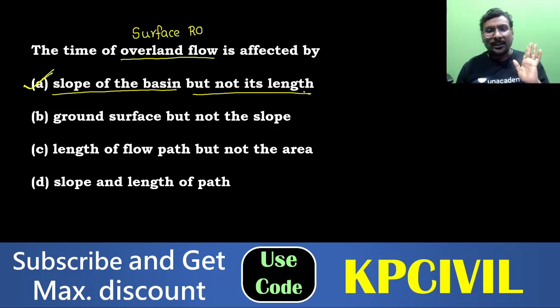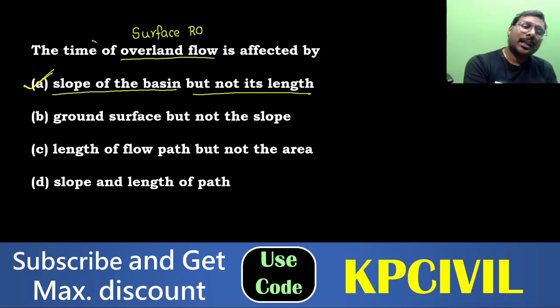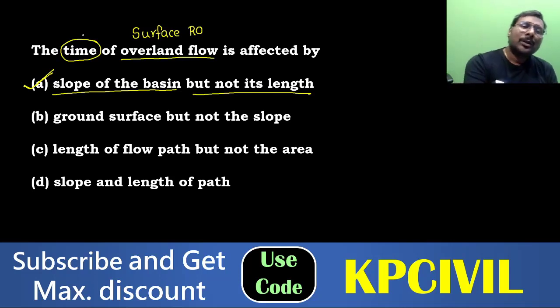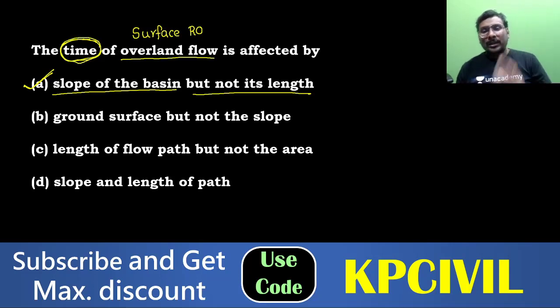Just remember like that. It is not about total surface runoff they are asking. They are asking about time of overland flow. Very important. We are thinking about surface runoff only, worrying how to consider surface runoff, how to think about overland flow. But the question is not the full overland flow. The question is time of overland flow. Time of overland flow depends upon the slope of the basin but not on the length.